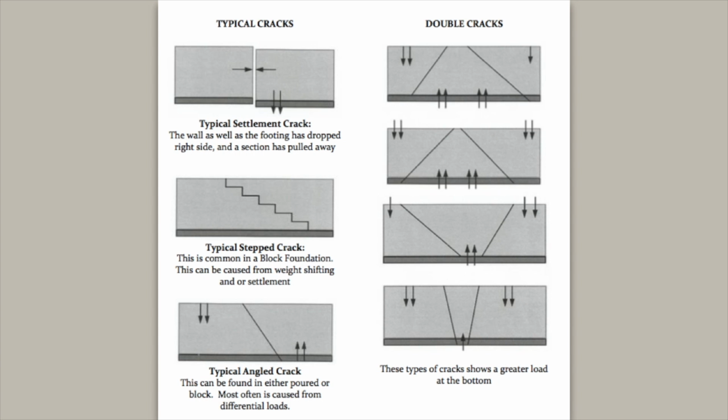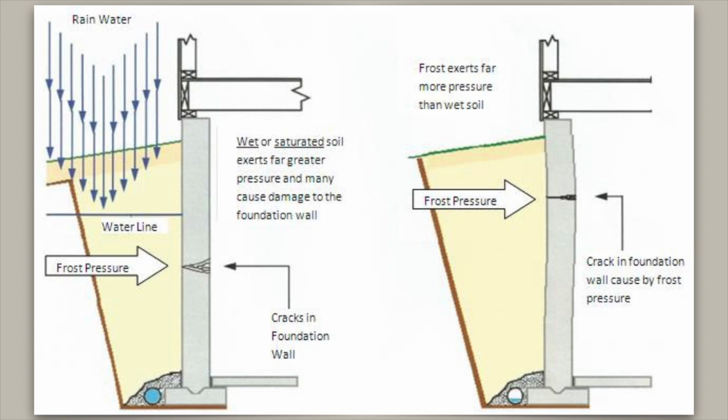The following images below are examples of cracks that could be seen during an inspection. Worst type of crack: horizontal. Vertical cracks are normally due to the settling of the house and foundation. This type of crack is not considered a structural concern if it does not involve the footer. Horizontal cracks are considered a structural concern. Horizontal cracks are considered the most dangerous. If a horizontal crack is displaced and the entire wall is not plumb, it should be reported as a defect.